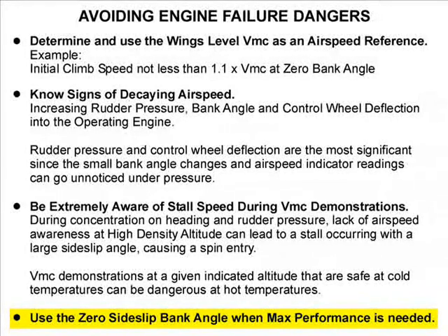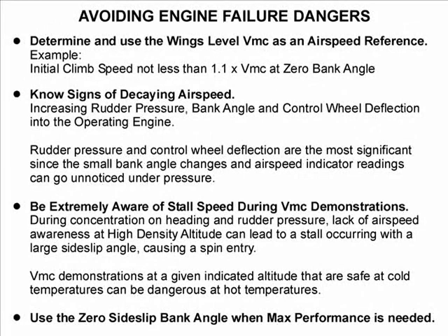Finally, use the zero side slip bank angle when max performance is needed. Remember that safe operation with an engine out is all about airspeed. If you sense increasing rudder pressure or wheel or stick deflection toward the operating engine, push the nose down, even if it results in a descent. It is better to land under control almost any place rather than spin vertically into the ground.